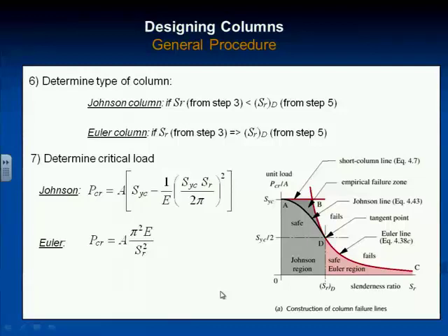Uncertainty of loading, uncertainty of what the real strength of that piece of steel is I just bought from the store. The book says it should be 45,000 psi. I test it, I find it's only 42. So there's uncertainty everywhere. So seldom do we know our information well enough in machine design to use less than about 2. That's what I shoot for.